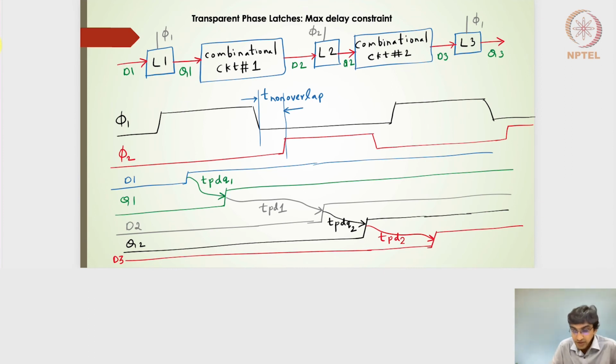Right, so let's proceed further to the next kind of sequential elements, which are called latches. Generally, latches are not utilized in the way we have utilized the flops. The flops are utilized with respect to the clock edges. So we have the combinatorial circuit between two subsequent flop elements, such that the output of combinatorial circuit 1 will be captured in the second clock edge, and so on. But latches are designed in terms of levels. They operate in terms of the levels.